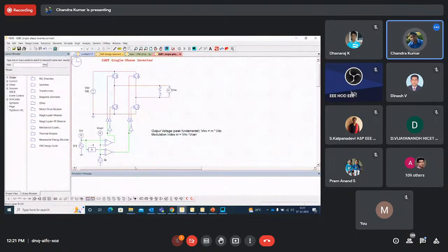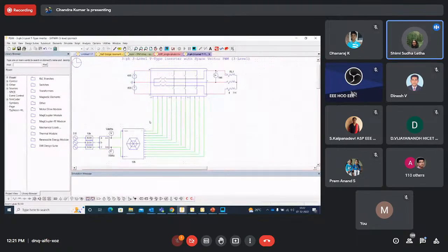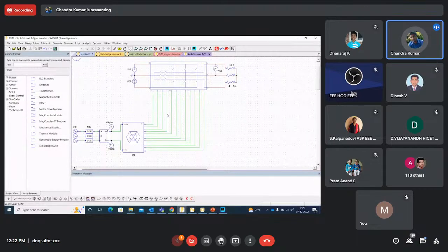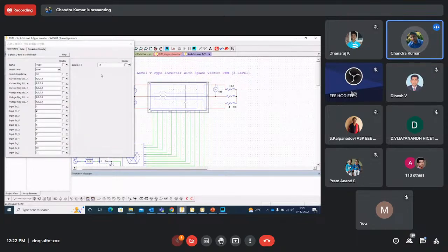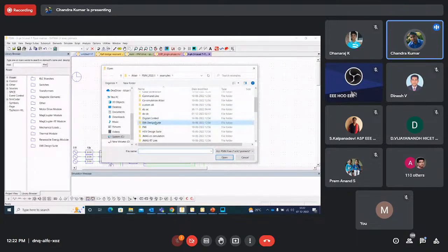See, this is a simple inverter. Okay, IGBT one, single phase. So I could understand the inverters according to the standards, and we can just do it for a range, because you can also give the manufacturer's data sheet. Click on here, you go to thermal. You can go to ideal level, and the actual thermal level is also there, where you can calculate switching and conduction losses. It's an amazing tool for power electronics design and analysis.